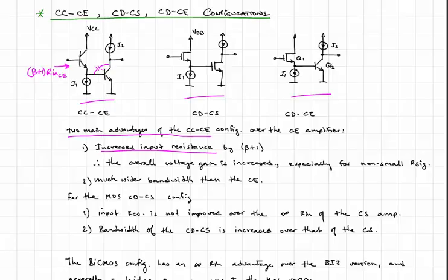And so the polarity of the feedback is a negative one, such that if the transistor turns on harder, the collector voltage falls. What will tend to happen is current will flow from the base through that capacitance to the collector side. And so the flow of that current is actually stealing or robbing base current, which will have the effect of turning off the transistor and therefore slowing down the fall of the collector voltage.